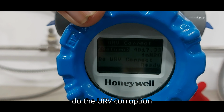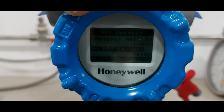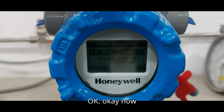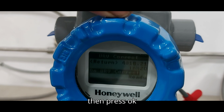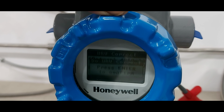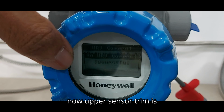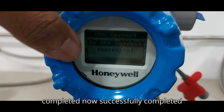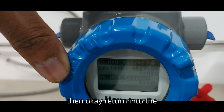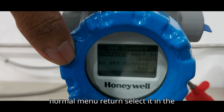Do the URV correction, down arrow and enter. Now 12 bar is reached and stable, then press OK and confirm is OK. Now upper sensor trim is successfully completed. Then return to the normal menu, return, select it, enter,